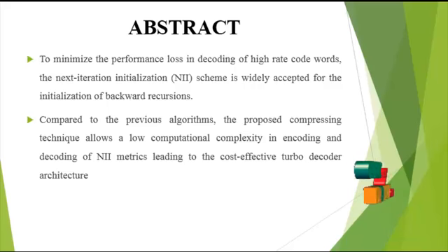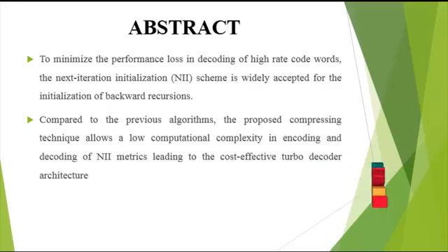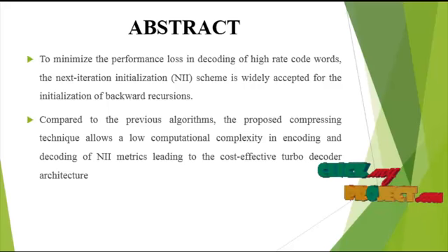The turbo code is one of the most attractive forward error correction codes which can provide near optimal bit error rates of Shannon's limit. Due to the fascinating error correcting performance, the turbo codes have been applied to various wireless communication systems. For achieving a high decoding throughput, an aggressive puncturing on long turbo codes is normally defined at the recent wireless standards. The extreme case of 3GPP LTE advanced specification, for example, necessitates a code length of 6144 bits and a code rate of 0.95.